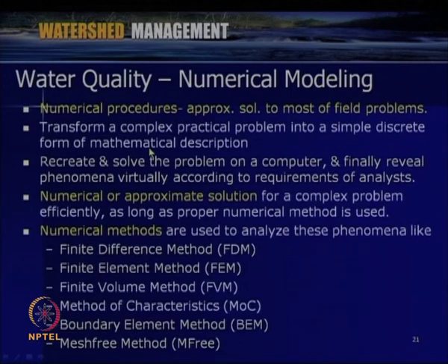There are a number of numerical methods available. Over the last few decades, with the advancement in computer technology, a number of numerical techniques have been developed, like the finite difference method, finite element method, finite volume method, method of characteristics, boundary element method and mesh-free methods. Depending upon what type of process we are trying to model, or what kind of contaminant within the aquatic environment, either surface water or groundwater, we can choose specified models and technology. Nowadays a large number of models are available in the market, based upon various numerical techniques like the finite element method or finite difference method, which are the most commonly used numerical tools. We can choose depending upon the user's familiarity and needs.